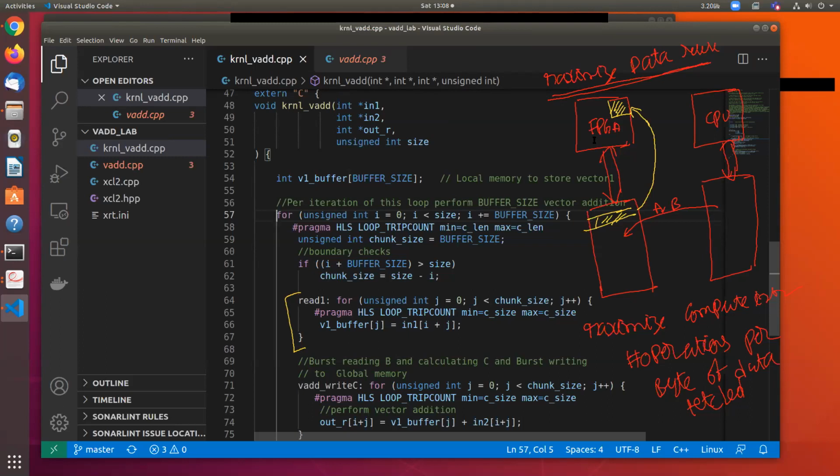So, depending on the FPGA and the platform that you use, you may not have access to the host memory directly, right? Or it may be slow because it basically communicates to the host through PCIe. The data still has to come from somewhere, so the CPU has to know which address to put the data to. It's not that there is a dedicated connection for data coming from the memory of the CPU directly to the FPGA. It still has to come through the host over PCI.